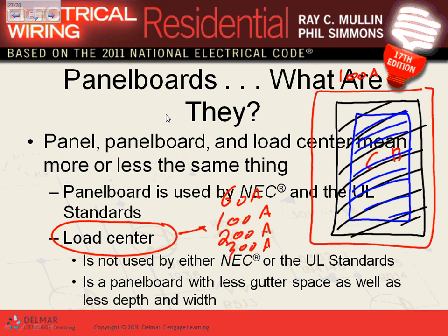So long story short, guys, if you have a 100 amp load center, it might look that wide, right? The same 100 amp panel will look wider, deeper, taller, or longer. Bigger equipment. Why? Because they want to allow people to maneuver the circuit breakers and the conductors, with more room for you to pull the conductors through the gutters on the panel. That's all we're going to say.